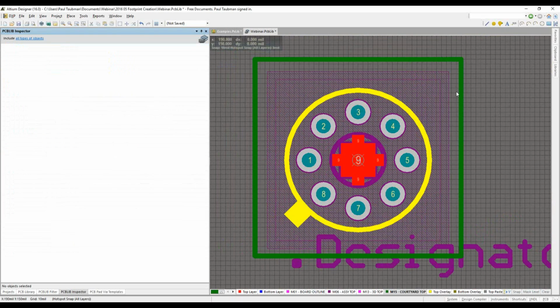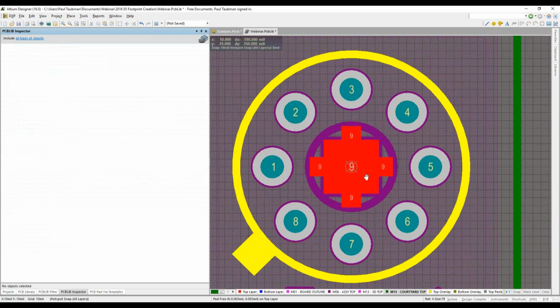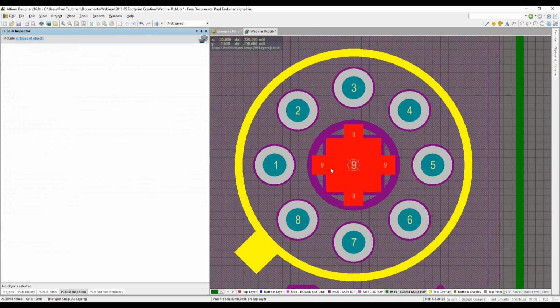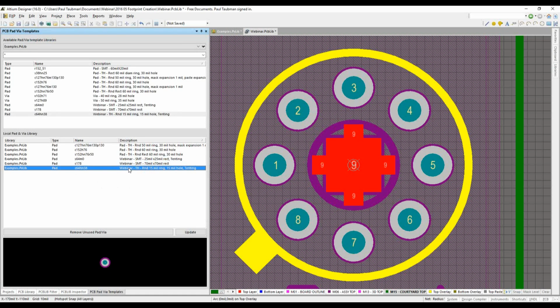So I have those pads in there, but I also have to put some through holes here. The idea here is to allow me to put some solder paste over here and then move off these through holes so that the solder doesn't go into them. I'll show you something else I did to these too, but wait a moment while I put these other ones down. So for this webinar, I'm going to place these.